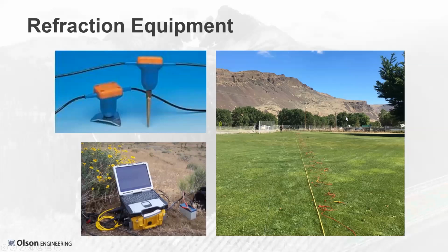Our seismic refraction equipment is pretty straightforward and pretty similar to what you'd use in just about any other active source seismic survey. You have geophones, vertical component if you're doing a P wave survey, and horizontal component if you're doing a shear wave survey. You have a seismograph. This right here is a Geometrics Geode, which has 24 channels. And then you need some cable to connect everything together.